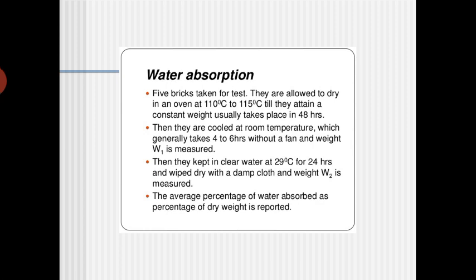This is also a very important property, because with the water absorption property, the durability aspects of the bricks can be assessed. When you keep bricks in rainwater, whether they are going to absorb water, whether they are going to be damaged, or how much damage is going to happen, can be analyzed with the help of the water absorption property.